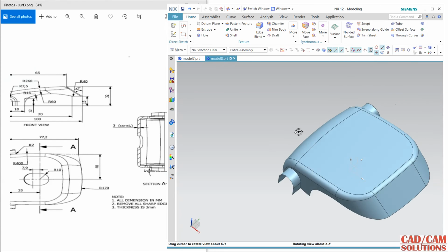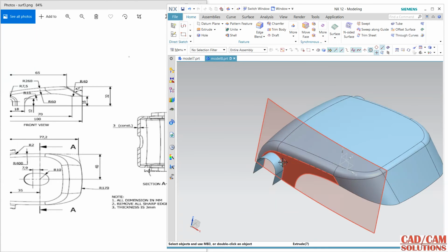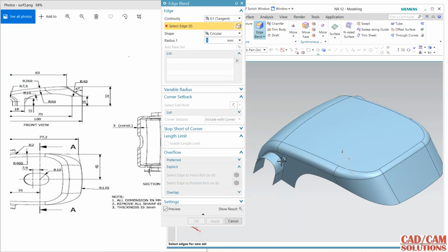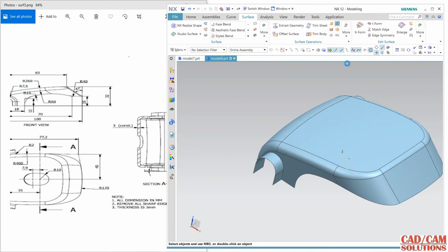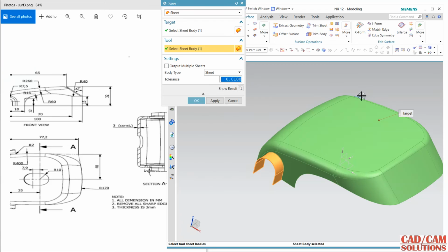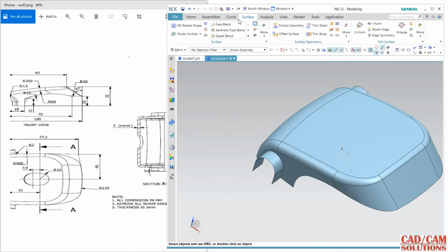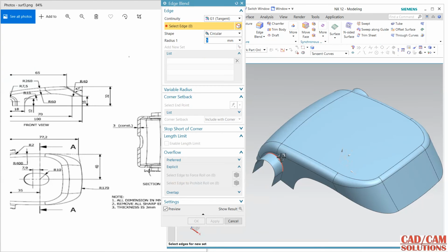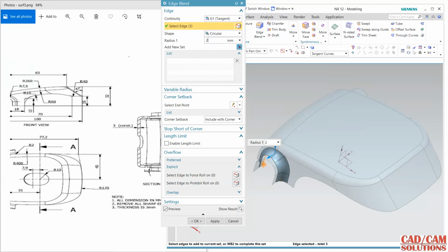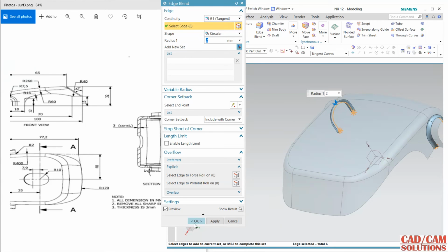Okay, now it is here, and here I want to apply some fillet, so these all are not connected either. So go to Sew and select all the surface and Sew all. Now the fillet is 2 radius, it is 2, and same here 2. Okay,